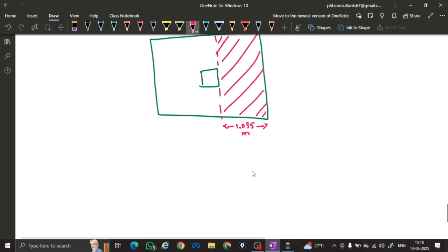Now we will calculate the moment. How to calculate? We have a square footing, so the moment in the x direction and the moment in the y direction are both the same. For that purpose I will calculate the moment only one time. So the cantilever formula is W L square by 2, where W is the net upward pressure.